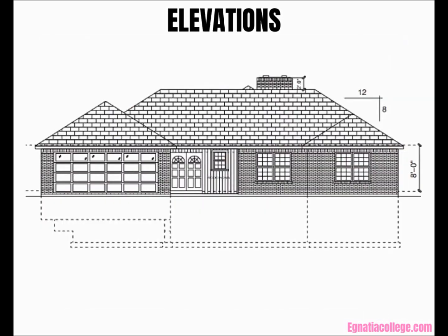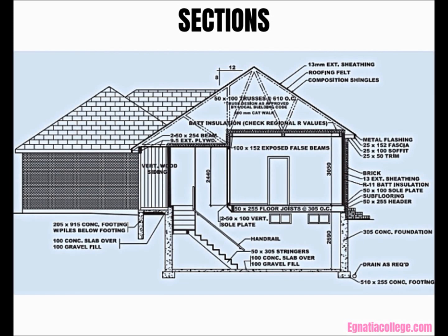Elevations. An elevation is a side view of the building. Elevations are used to show heights and widths. Elevations are commonly used to show outside walls, interior walls, and the placement of such things as cupboards and equipment. This figure shows the front, south, elevation of the house. Sections. A sectional view of the building, after a portion of the building has been removed, is used to show the interior construction details of the building. This figure shows a portion of section AA on sheet 4.